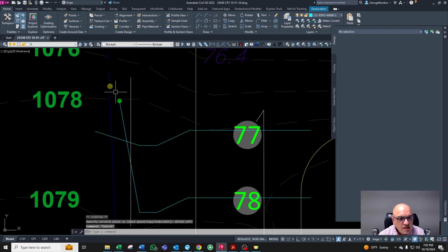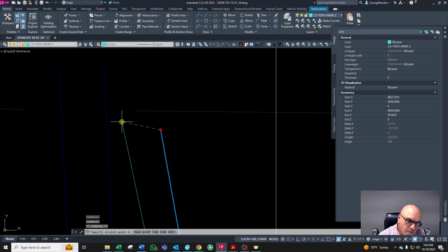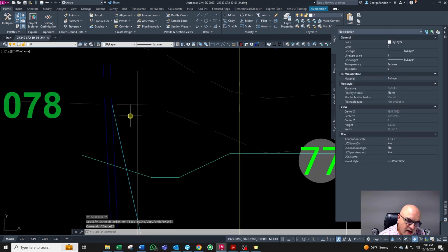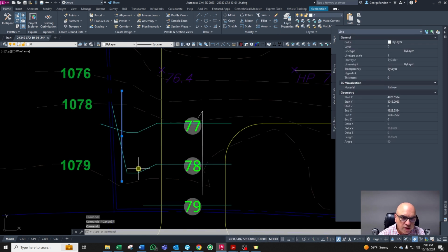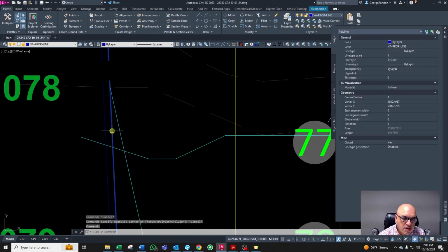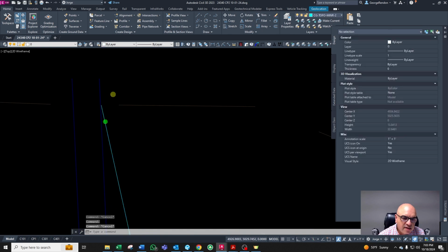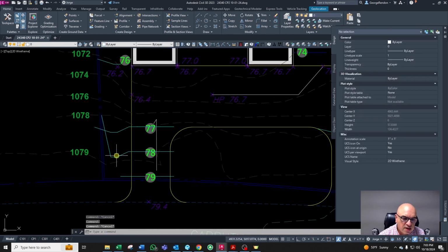Basically you need to come like 0.5 feet from the property line, and then you can tie your proposed contour to it. This is a construction line. So we tie the existing one to the proposed one.